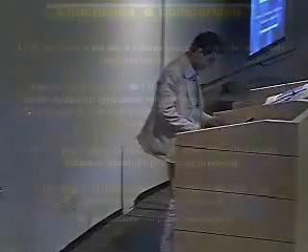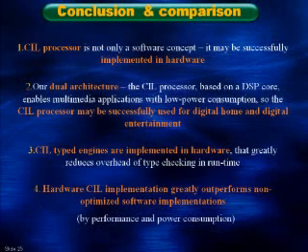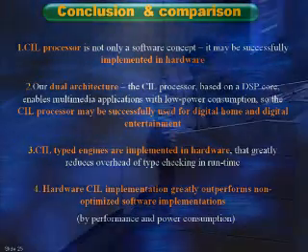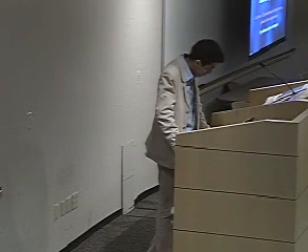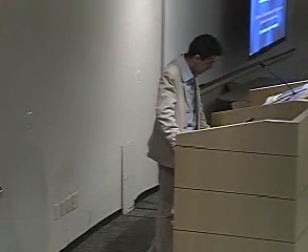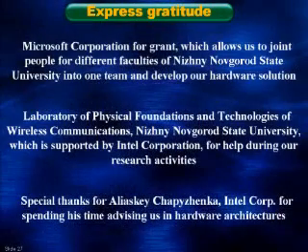And this is the conclusion. The CIL processor is not only a software concept. It can be successfully implemented in hardware. And our dual architecture, the CIL processor based on a DSP core, enables multimedia applications with low power consumption. So the CIL processor may be successfully used for digital home and digital entertainment. CIL type engines are implemented in hardware. And hardware CIL implementation greatly outperforms non-optimized software implementation in performance and power consumption.